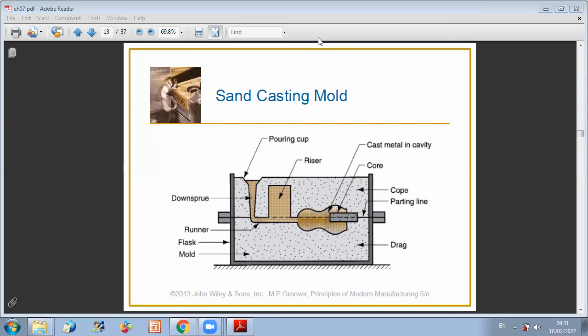Why, for the internal part, did you say we make a smaller mold? Look, let's say you want to have here shrinkage. When solidification happens, shrinkage occurs directly in the direction towards the metal. So the part from the outside will retract in this way, so it will be reduced in dimension.